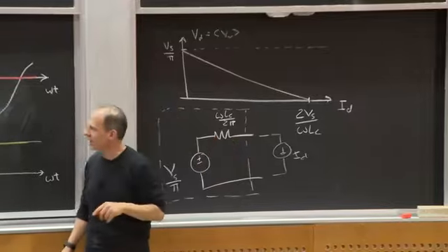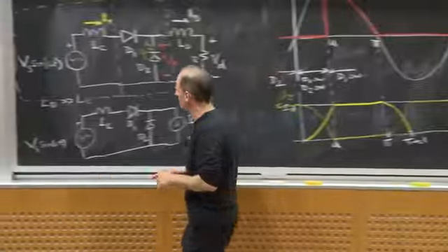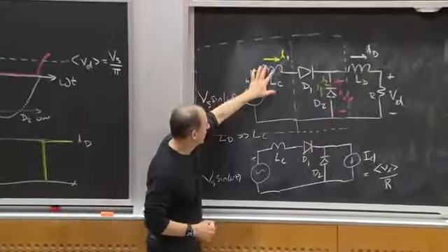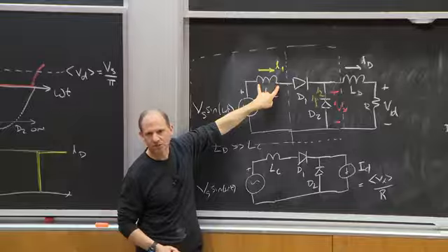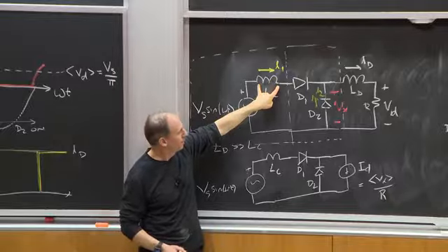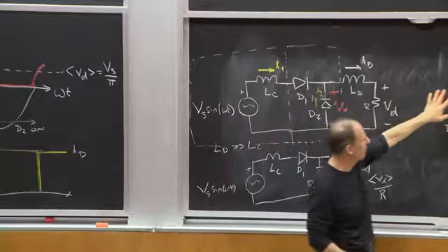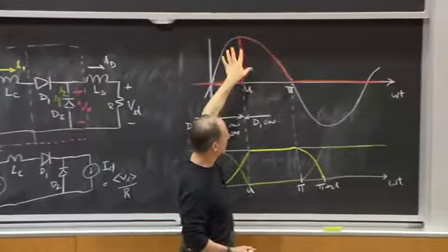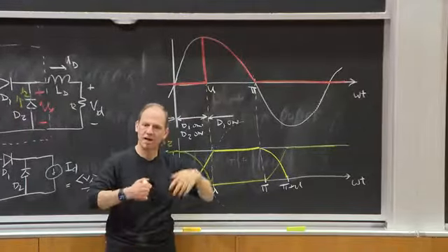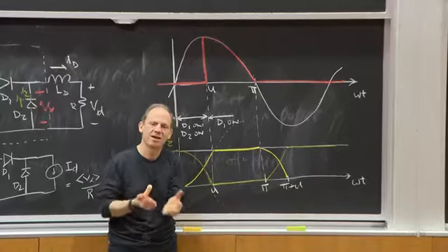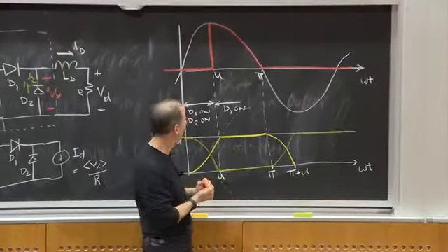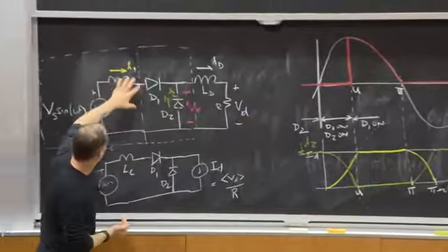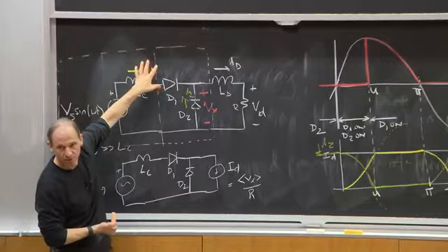What's happening instead is that each time this voltage swings positive, I've got to take some time to charge up this inductor to the right current, okay? And that time eats away from the time at which I generate my positive pulse, which is rectified to give me output voltage. So I'm sort of eating into my ability to synthesize a DC output voltage, okay, because I have to charge him up, right?